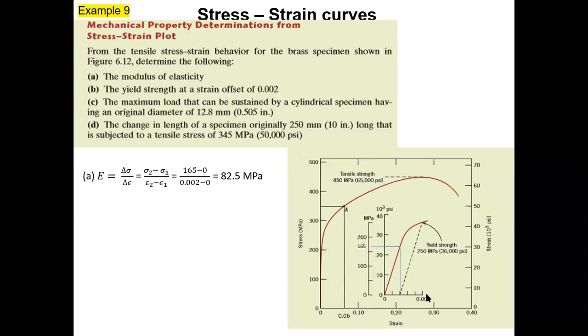Any method is correct. Remember, it is always the stress divided by the strain. For the slope you have to choose 2 points. Then you can divide it like this to find the elastic modulus.